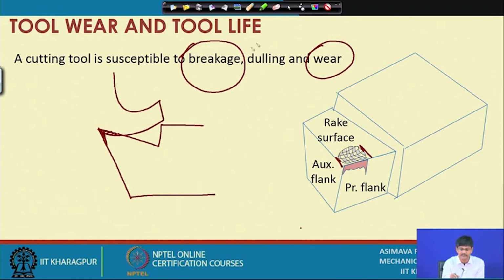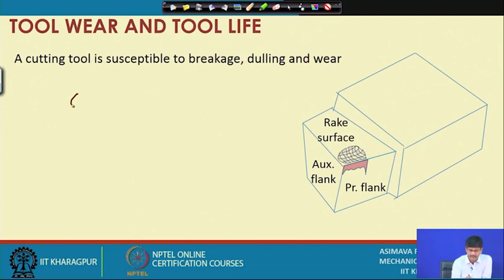That is to be avoided at all costs. The cutting edge itself individually might be dulling off very fast without this effect manifesting itself before that. Those things we are not considering when we are talking of the gradual phenomenon of wear. This takes place very gradually. But when do we stop? When do we stop using it? What are the indications first of all?